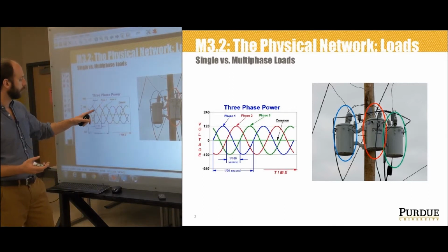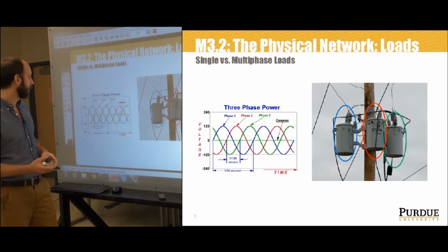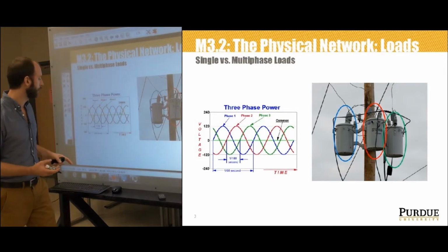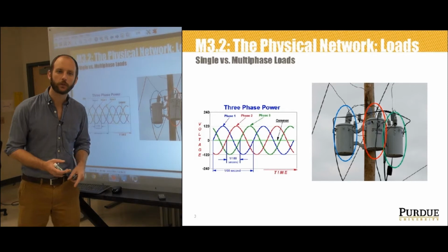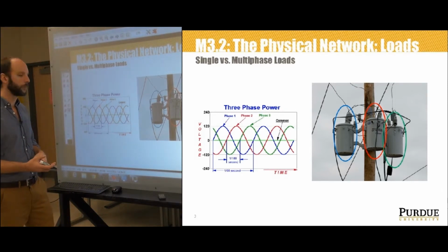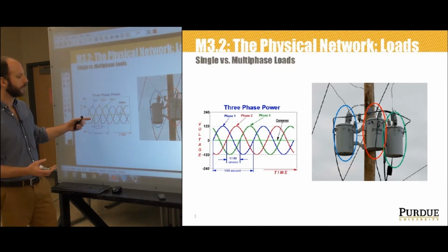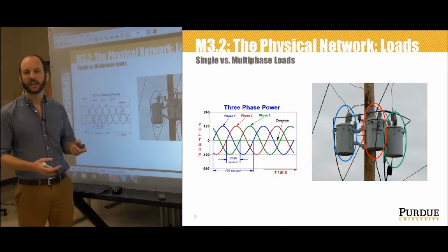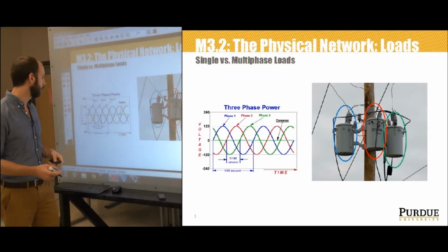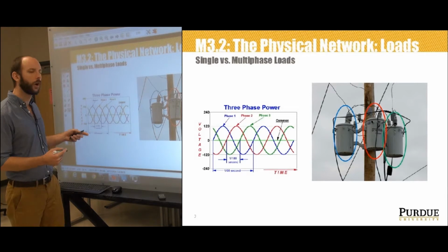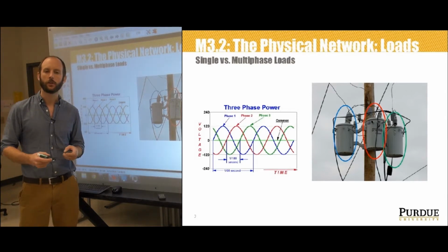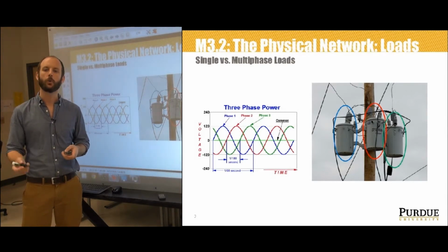So it's got a zero phase shift, and then we notice that red has 240 degrees of phase shift on this diagram, and green has 120 degrees of phase shift. We could have easily said that red has negative 120 degree phase shift too. That would have been an appropriate way to describe that, negative 120 degrees and 240 degrees being an equivalent angular rotation.